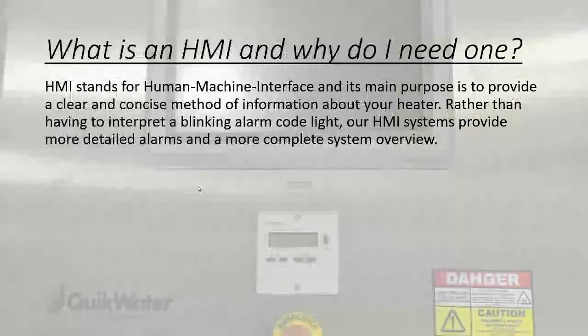One of the main questions we get here is not so much what is an HMI, but why do I need an HMI? An HMI stands for Human Machine Interface. That's a little tech sounding, it's a little scary for some people, but it's really very simple. It's the touch screen that translates all the PLC's bits and bytes into understandable information about your heater. It doesn't change anything about the way the system works at all. The system works the same. It just improves our ability to understand the system as a whole.